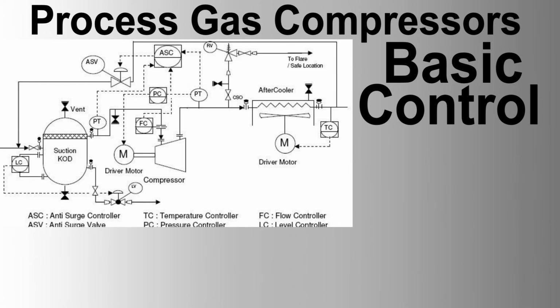#1 Control Strategy Modifications. A. Master-slave control. Implement a master-slave control strategy where one compressor, the master, dictates the operating conditions while the other compressors, the slaves, follow. The master compressor's control system sends set points to the slave compressors to balance the load.